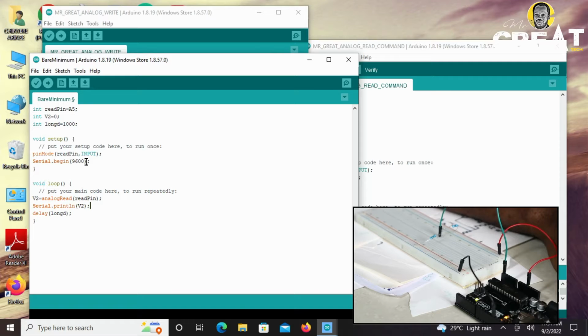You have different types of baud rates. This is 9600. There are other good baud rates that you can also input in this place. When we come to this as a topic on its own, we can treat it. But for the sake of this program to run, just put it that way. Serial.begin sets up your serial monitor and your baud rate, so it has to be in the void setup.